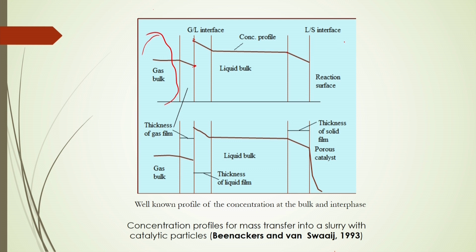Again, if we consider the solid phase here, the liquid solid interface, in this case you will see that at the solid surface there will be the reaction surface, and adjacent to this solid surface, that is the liquid solid interface, there will be a thin film, and the concentration will be decreasing, and then again at the solid surface the reaction will take place there. So, this is the concentration profile when the component reacts with some other reactant, and how the mass transfer happens in the fluidized bed there.